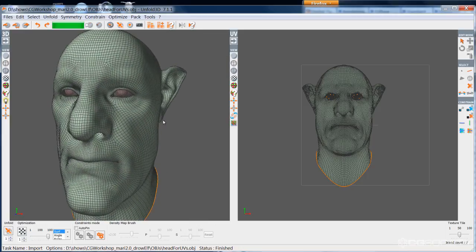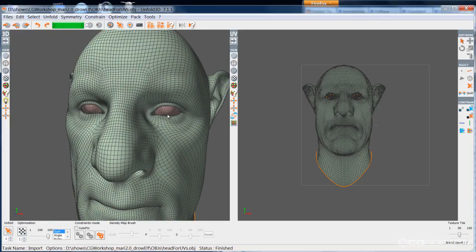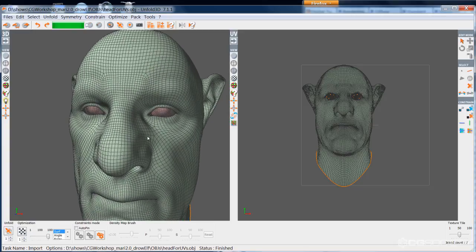So let's get started. I'm going to hide some of the geometry so I can just focus on the mesh of the skin. If you hold down Tab, it's going to bring up this hot wheel for different selection modes. There's face, there's object, there's vertex, and there's edge. I only use edge mode and object mode, so I very rarely use these two.